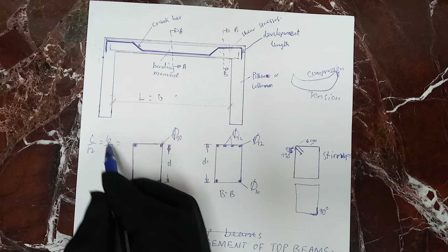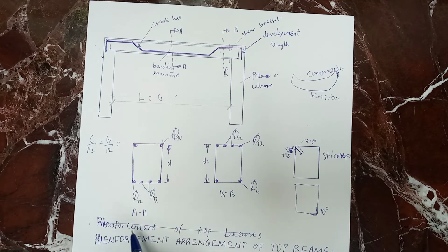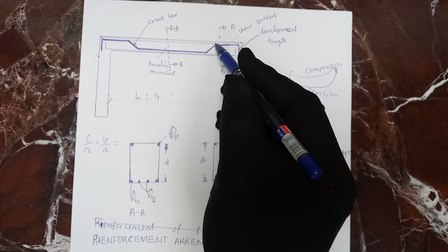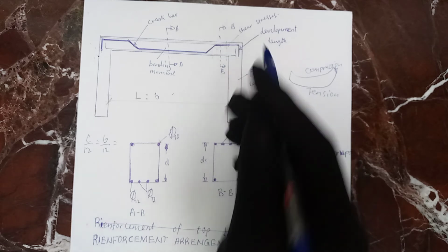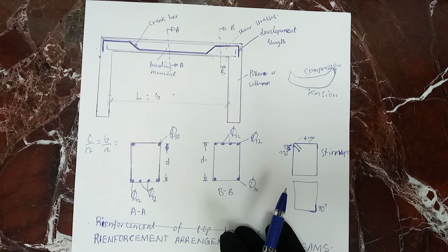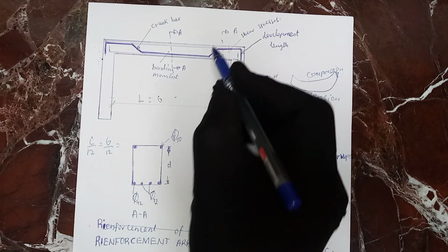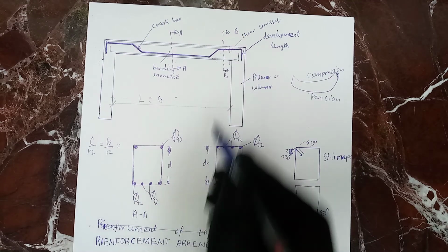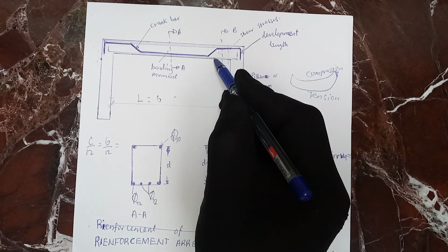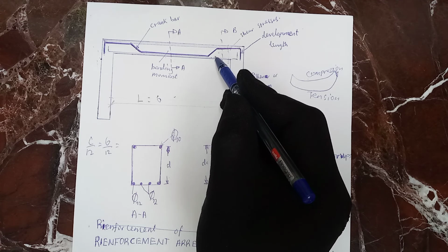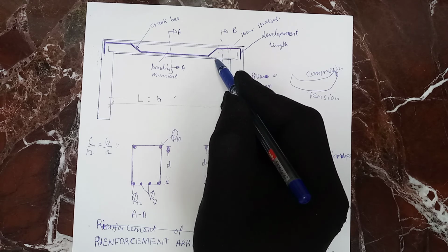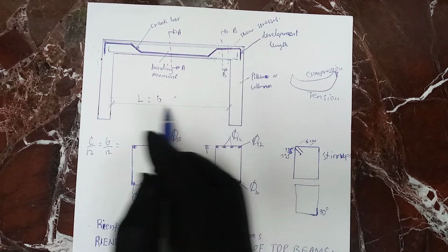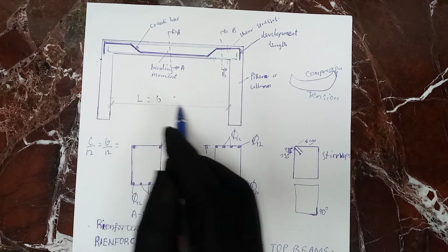You can then use it as the thickness of this beam. So if the width is 20 centimeters, the depth should be at least 35 or 40 centimeters, because the span is already 6 meters.